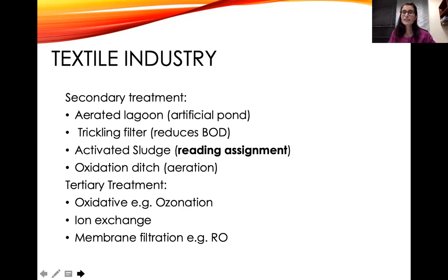The suspended solids can form a very thick film outside, because there is a film growing on the wall of the filtration. It's a high pressure filtration system, which means you're applying a lot of pressure on this reverse osmosis membrane to take all the clean water out, which is possible. I mean, you can reduce the pressure and clean the membrane continuously to make sure you do that. But that increases the work for you, and it's expensive because it uses a lot of power.